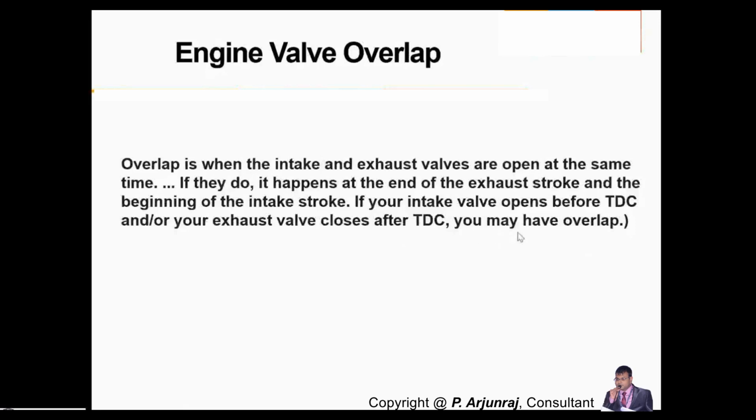Looking at the diagram, you may feel that it is the period between the intake valve opening before TDC and the exhaust valve closing after TDC. But correctly speaking, it is the period of time where the inlet valve opening and the exhaust valve opening happen at the same time. That is the correct meaning.